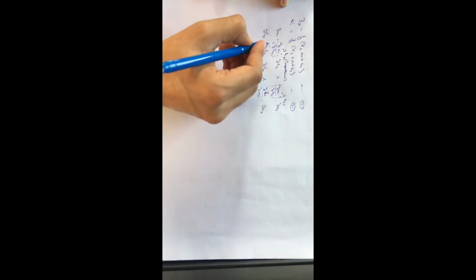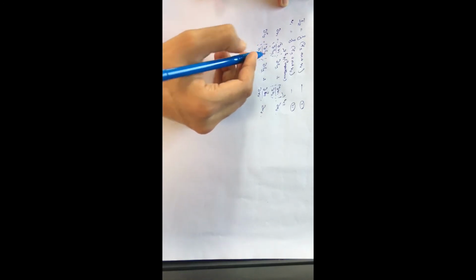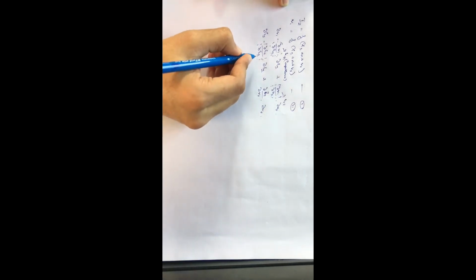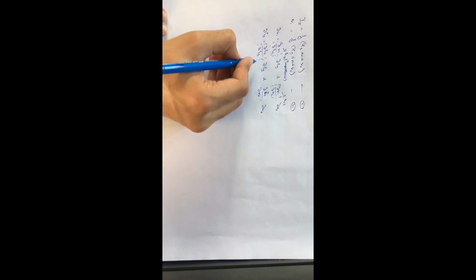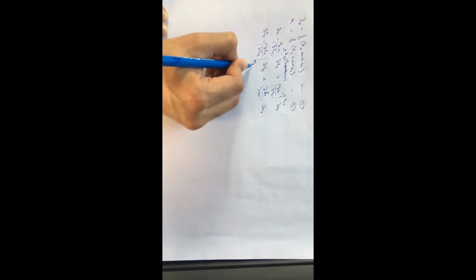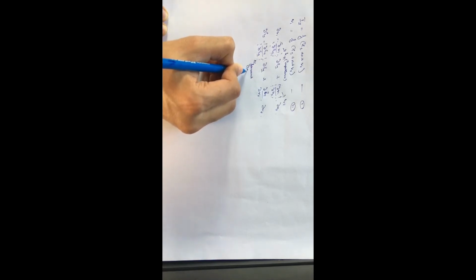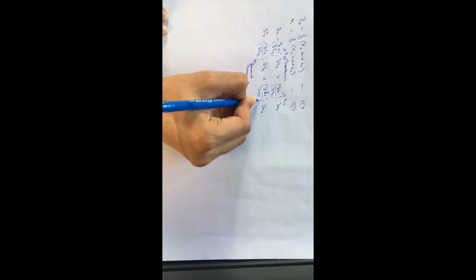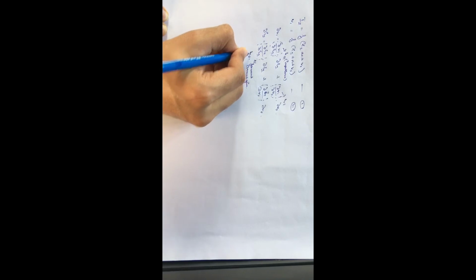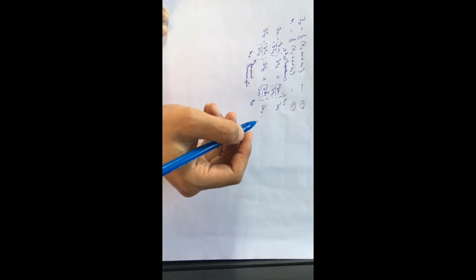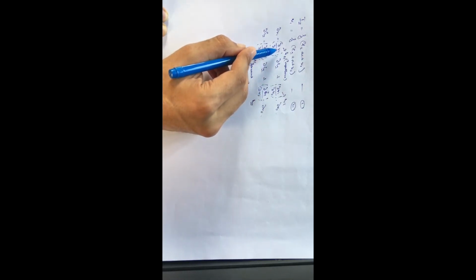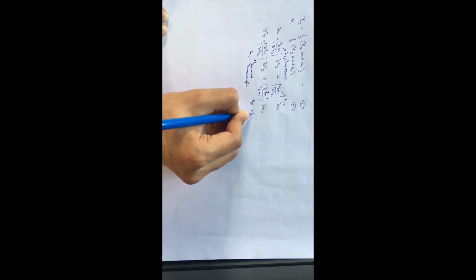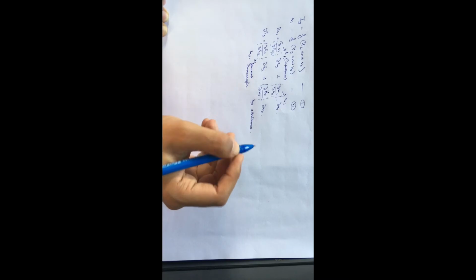And this is also a dimensionless parameter because current and current get cancelled out in units. But as we can see, I2 by I1 gives us forward current gain. We can write this as H21, and we can write this as H22. We know that V by I is impedance, but I by V is admittance. So we have four parameters.